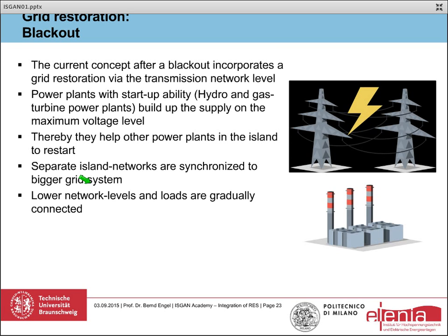Grid restoration in case of a blackout. The current concept after a blackout incorporates grid restoration via the transmission network level. Power plants with start-up ability, hydro and gas turbine power plants build up the supply of the maximum voltage level. Thereby they help other plants in the island to restart, and separate island networks are synchronized to bigger grid systems. Lower network levels and loads are gradually connected.